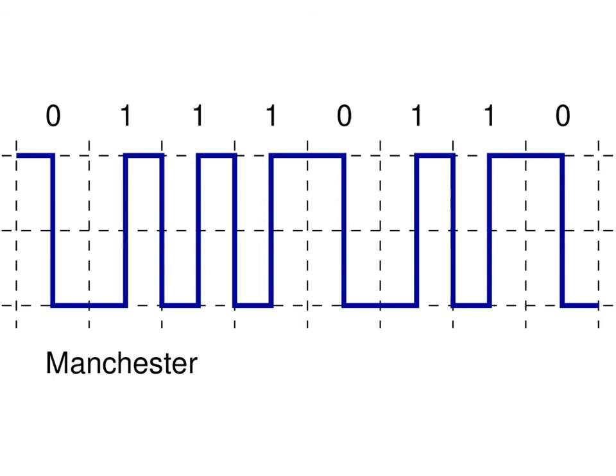With Manchester encoding, in the same conditions, we'd say the signaling rate is what? 1,000 pulses per second, a maximum. In some cases we don't change, but we define that the signaling rate in this case, because every 1 millisecond we potentially change, so the signaling rate is 1,000 pulses per second, or 1,000 signal elements per second.